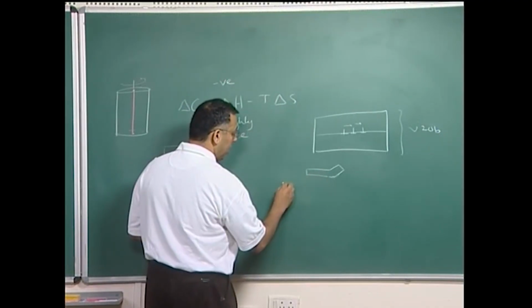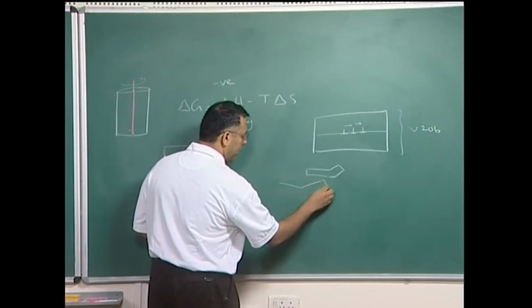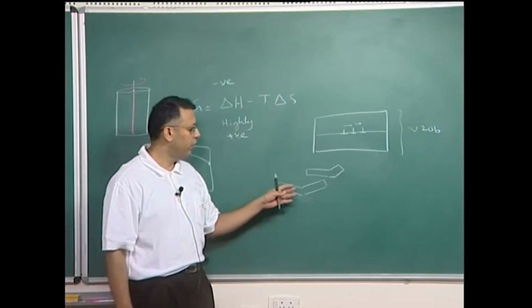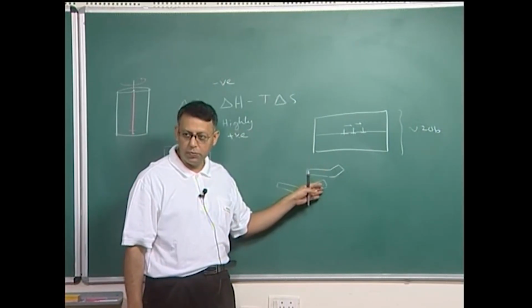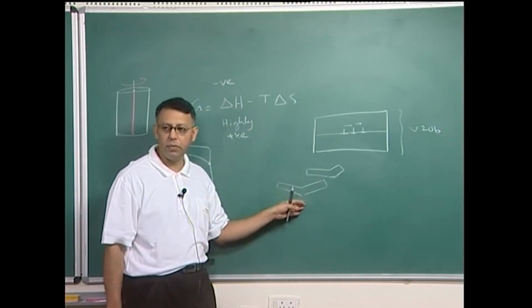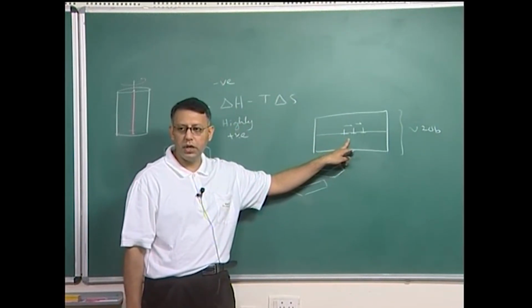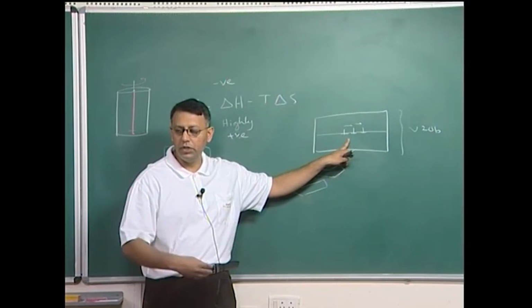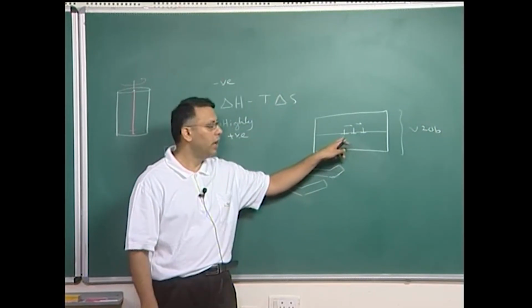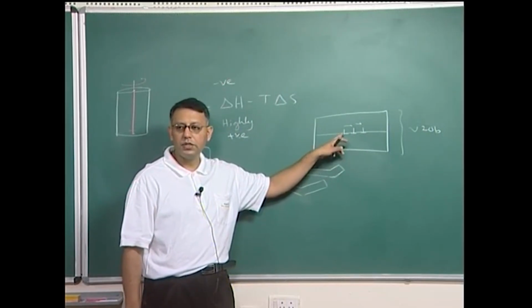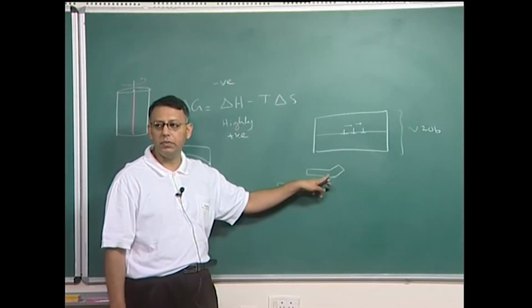This plastic deformation changes differently as I move the dislocation. Suppose I put it right in the middle of the plate, then it will bend a little differently compared to the case where it is positioned towards a free surface. Therefore, it is exploring various configurations, and this is permanent deformation, but since it exists without change in energy, you can call it reversible. That means the two states are equivalent in terms of energy. So it is strictly reversible and it is plastic.